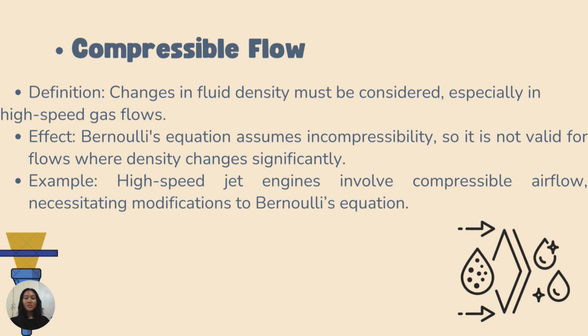Bernoulli's equation is derived under the assumption of incompressible flow where changes in fluid density are negligible. As a result, it is not valid for flows where density changes significantly, such as in compressible flow regimes. In compressible flow, variations in density directly impact the flow's behavior, altering the distribution of energy and pressure along the flow path.